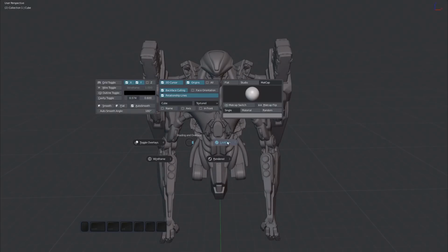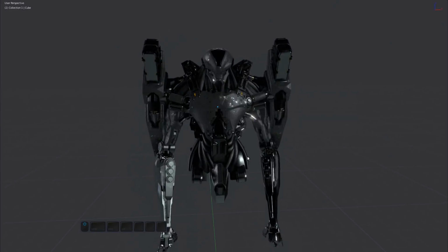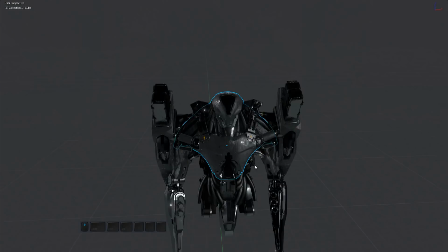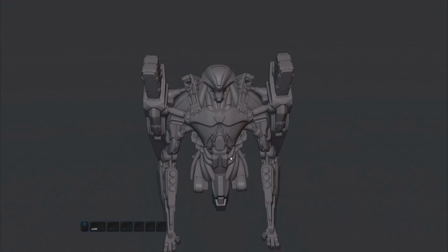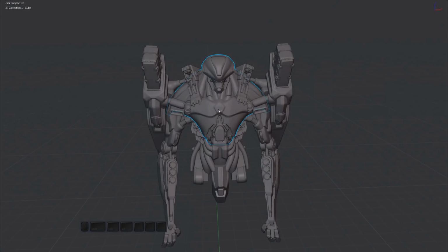On the right, you can switch to Look Dev mode, which is rendered in Eevee. The overlay toggle is now on the right. The shading pie remembers for which view the overlays have been enabled and where they have been disabled. So you can choose to have overlays enabled for solid shading, but disabled for Look Dev. Switching shading will toggle overlays automatically.